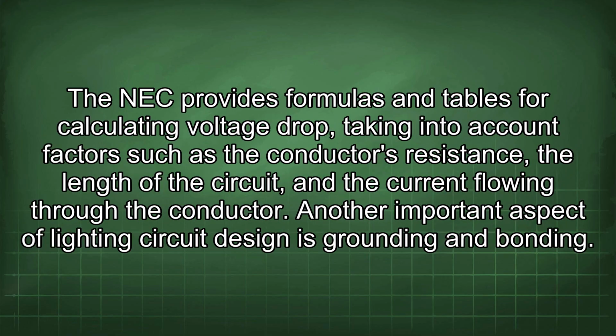The NEC provides formulas and tables for calculating voltage drop, taking into account factors such as the conductor's resistance, the length of the circuit, and the current flowing through the conductor. Another important aspect of lighting circuit design is grounding and bonding.